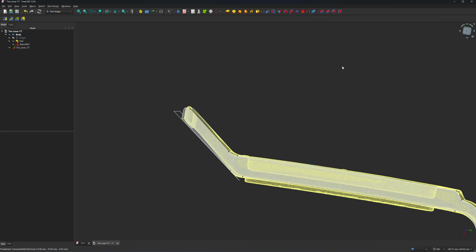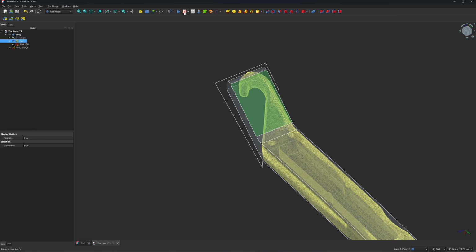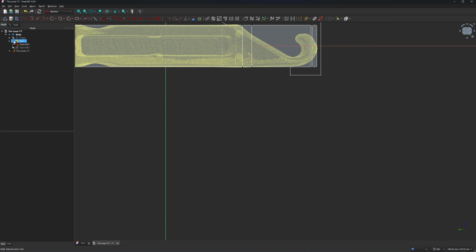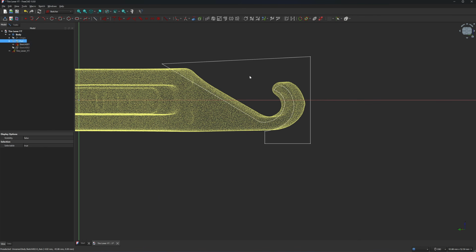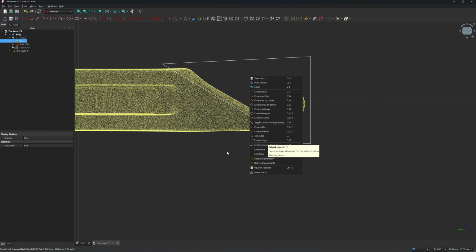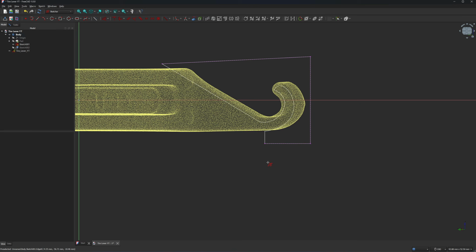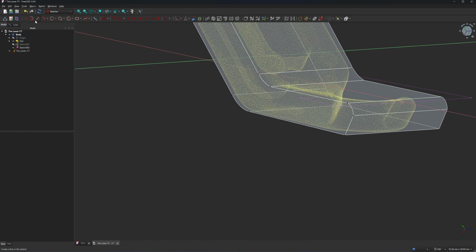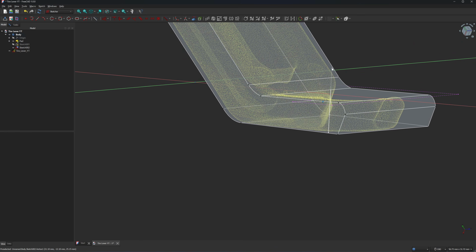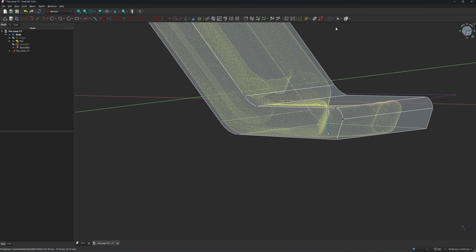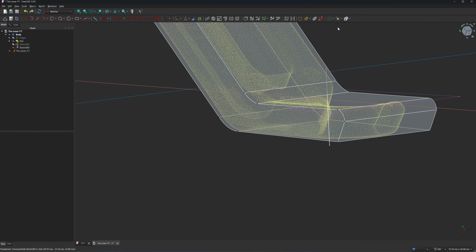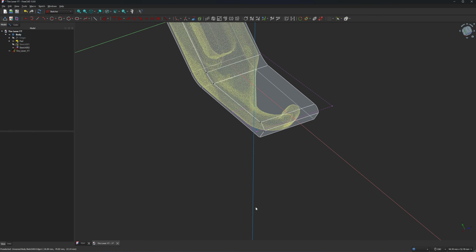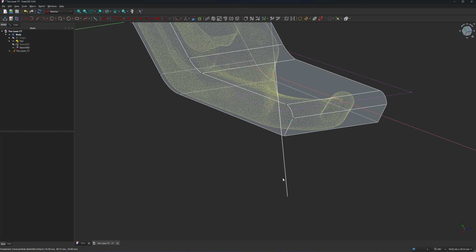I create a second sketch on this plane. Click on the plane, click on create sketch. Okay, now let me turn off the pad so it will be easy for me to trace. Next, I'm going to create external geometry. Project all this sketch. Okay, I start with this line. Same old line. Click on lines. You need to do a little bit of orbit to get this right. It looks easy, but it's not easy, isn't it? This tilted lever thing, I think it's here because it has a round corner.